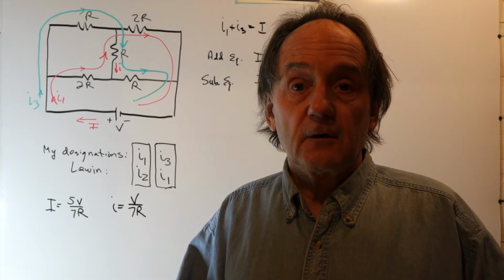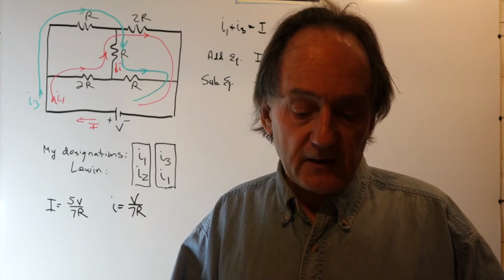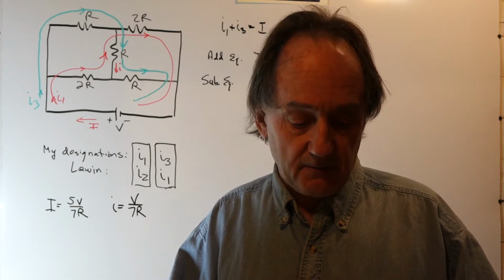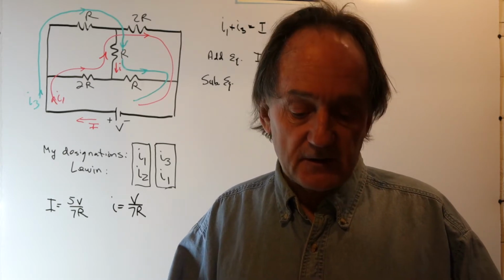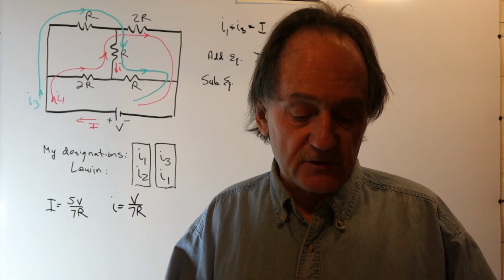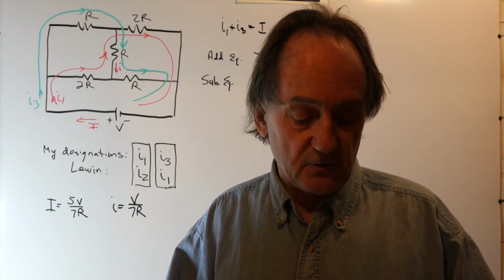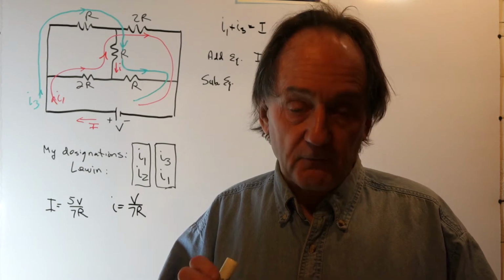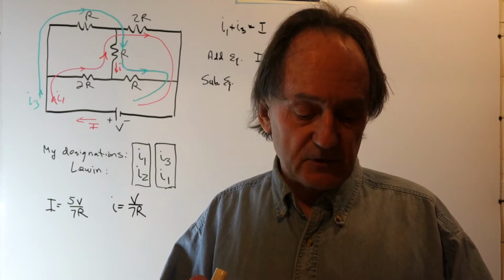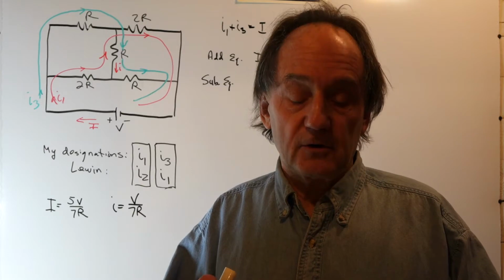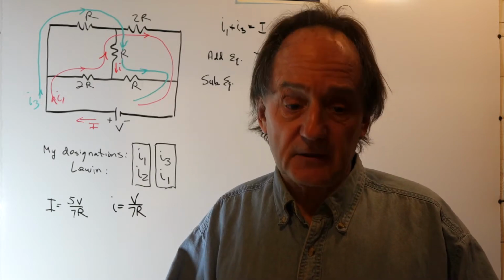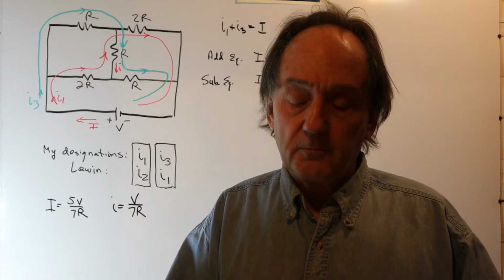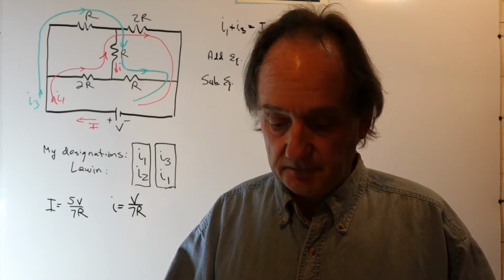The choice of two loop currents implies the current in the R-2R resistor pairs are the same. With this choice, a single current flows in each resistor except the bridge resistor, and that fixes the respective currents for those resistors. The assumptions made on the current symmetry need to be tested by writing Kirchhoff's voltage law in another loop to check for consistency.